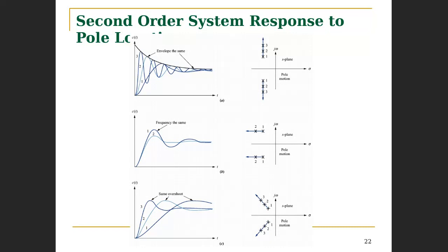Okay. Well, even though we term critically damped only for second order and higher order systems, a first order system cannot exhibit oscillatory behavior due to the nature of its transfer function. As I said, all first order systems look the same way. They look like the charging of a capacitor, and therefore we don't expect any losses. So you're quite right that it has a shape that is similar to a critically damped or overdamped system.